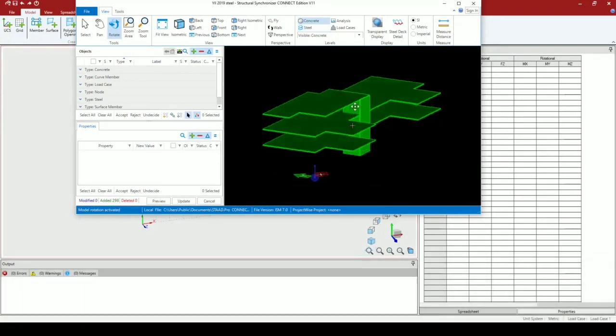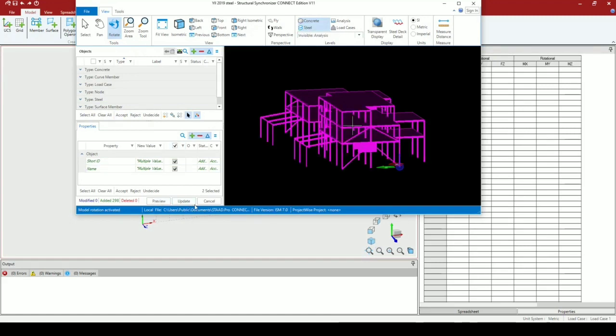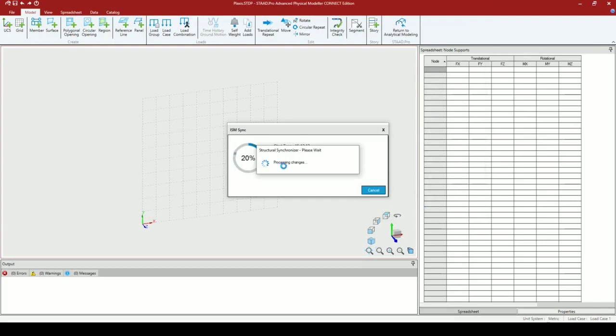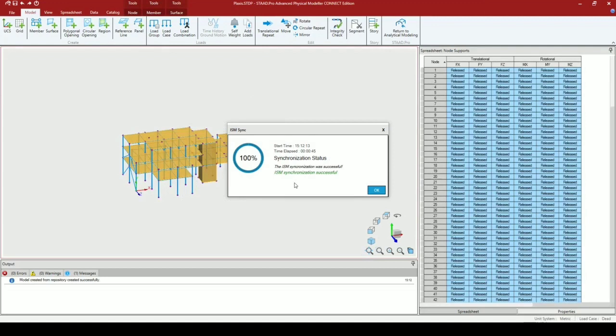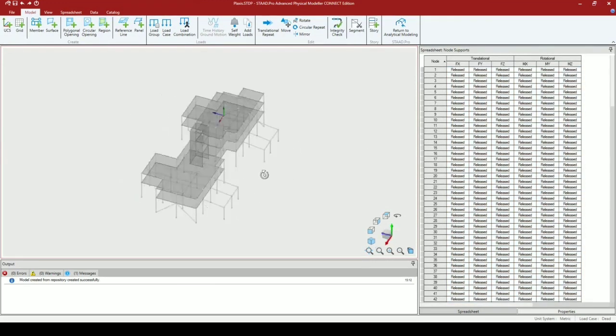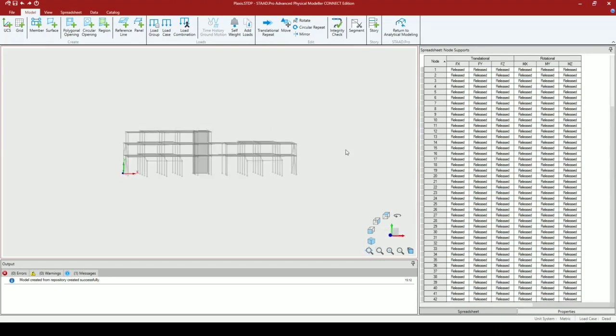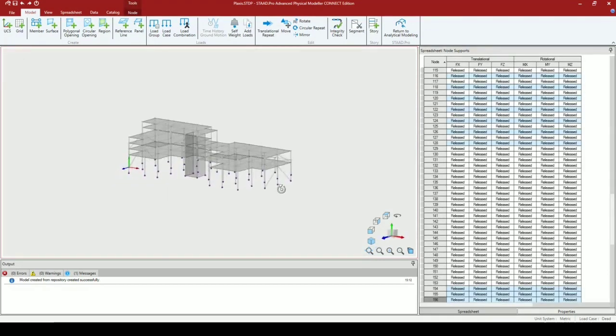this information is already predefined and clearly not something that we want to reproduce or recreate. So we're taking use of this information from that repository. We could actually filter out different parts of the model if necessary, define which bits we want and which bits we don't. But here it is already defined. We've got all of our surfaces, our beams, our columns, the central core, all of that ready to be converted into the analytical model that we want to perform the analysis on.